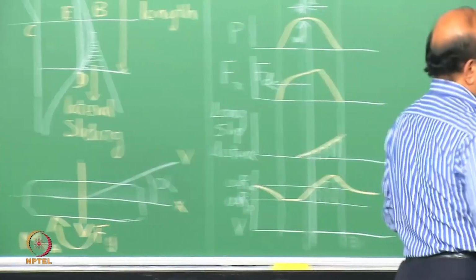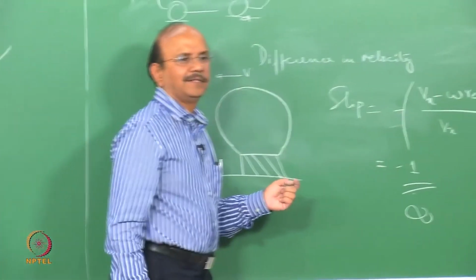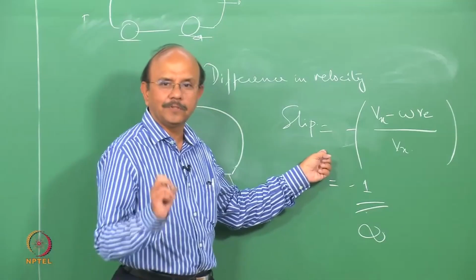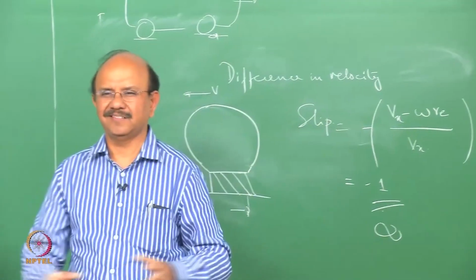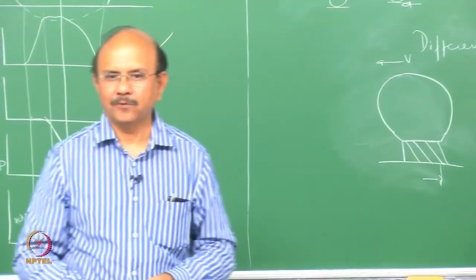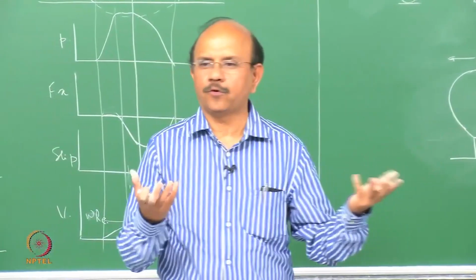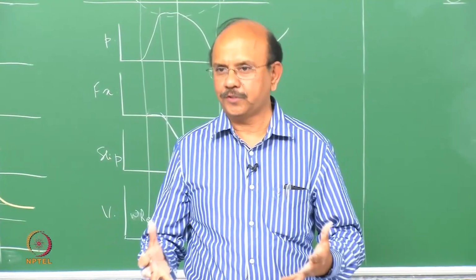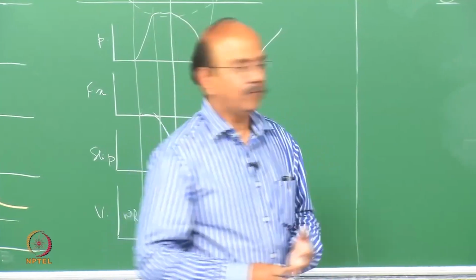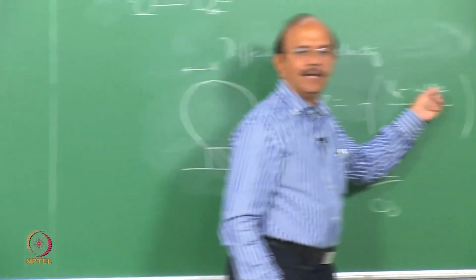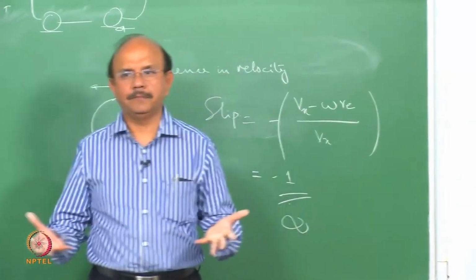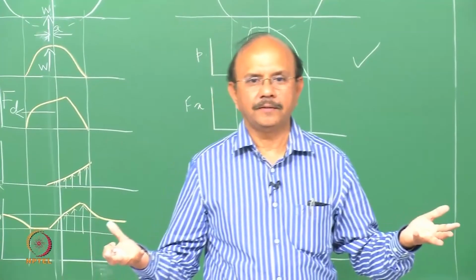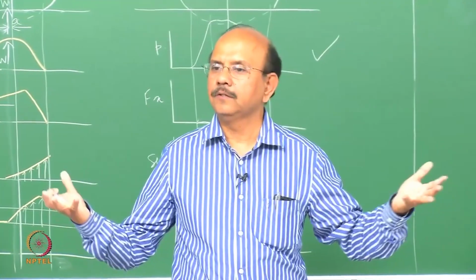An oxymoron: unless there is a deformation, unless there is a slip, note this, a force is not generated. Okay? You would think that when it slips, there is no force, but actually in a tire, when there is no slip, there is no force generated, number one. Okay? When the tangential velocity and this are the same, the bristles are not going to generate the force.